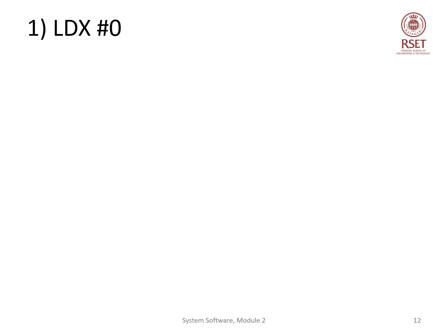Then the program counter: it is nothing but a variable that stores the address of the next instruction to be executed. For example, if you are at line number 2, your program counter will contain the address of line number 3. Now we'll begin with LDX #0.